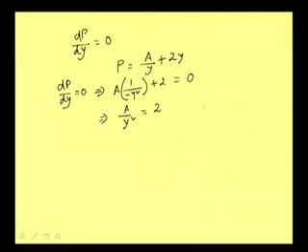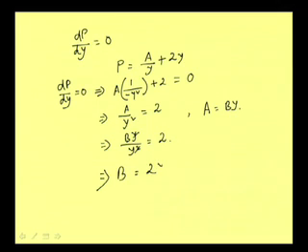Now, again we know what A is. Area is nothing but B into y. So, just replacing that, B y by y square is equal to 2, and this and that will go. So, B is equal to twice y. So for the most efficient section, or the most economic section, our relation is that B is equal to twice y.